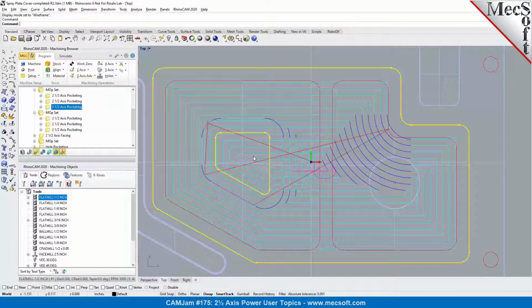So this gives you an overview of how tolerance affects your machining in 2-axis operation. I want to jump in here, Uday, and talk a little bit about tolerance stacking. You mentioned that, but I want to dive a little bit deeper. When we do arc fitting, we are fitting arcs to the toolpath points. We are looking at just the toolpath and fitting the arc geometry to it. Obviously, when we do that, we have to use a particular tolerance.